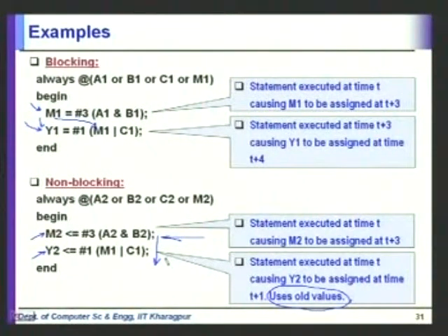All right. The non-blocking assignments are very useful for defining finite state machine behavior, where essentially what we mean is that the next state of the finite state machine is determined from the value of the current state and they are all independently determined, right, and so we can assign them using non-blocking assignments so that the right hand sides are all evaluated and then they are all assigned to the left hand side. Okay, and is that clear?